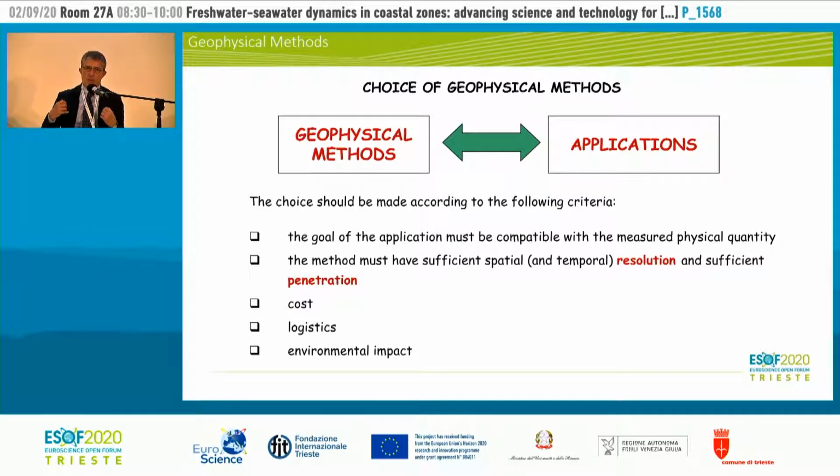But actually, when you run measurement at the ground surface, you must know what you want to see. And you must use the right method in terms of the physical properties of the subsurface that will answer your practical question. This is not always the case. Second, you must have a method that goes deep enough and with enough resolution, spatial resolution, to answer the question you want to answer. Everything else is less important than those 2 points.